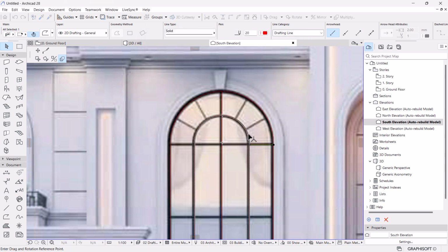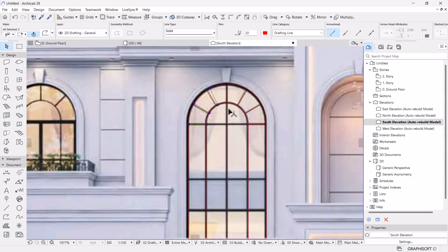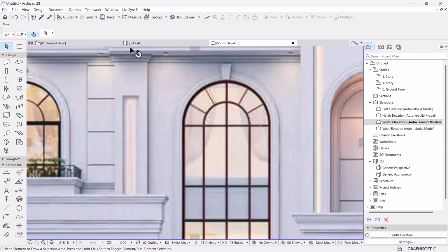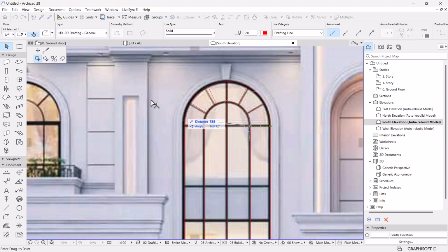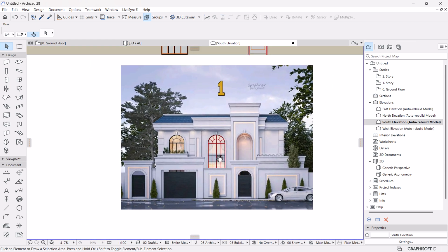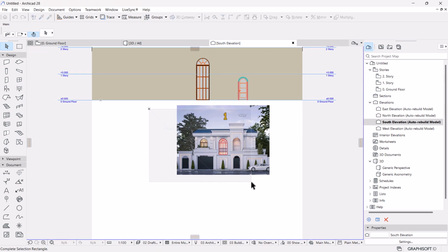I'm gonna select this as an arc. Okay, then click on that. Perfect. I'm gonna select these two and group. Control Shift M to mirror it to the other side. And this needs to, let me suspend the group. This has to go up across like that. Okay, let's select lines,